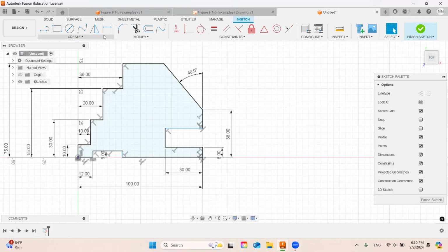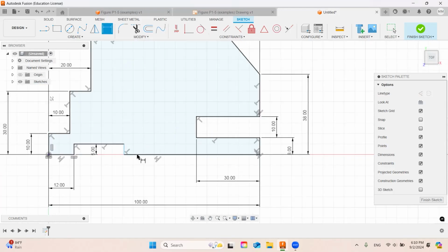And actually we do have those dimensions. So from here to here, this should be 10. Now it's fixed. And there's another one over here. I think it didn't show it in the thing, but it's actually shown in the SolidWorks. This one should be 25 actually. So make sure you put that one. This is 25.